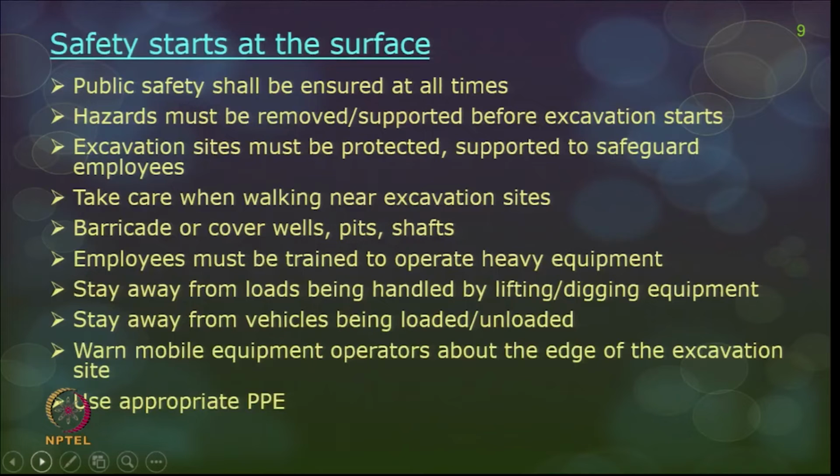So, you should be very careful when you are walking near excavation sites, and always try to barricade or cover any wells, pits or shafts, and the employees must be trained to operate any equipment. As a general precaution, when any lifting or digging equipment is operating, do not go near it. Stay away from the loads and stay away from vehicles which are loading and unloading.